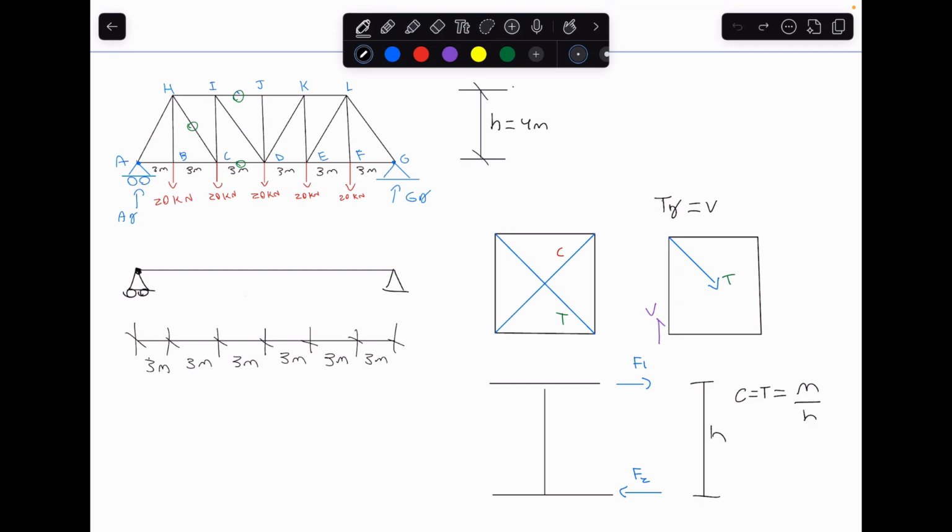Next, we're going to use the shear force diagram to get the diagonal forces using the single diagonal assumption. Basically, the assumption is that we used to have something that looked like this in the panels, one brace in compression and one brace in tension, but all of the compression braces have buckled. Therefore, we're left with a bunch of single diagonals. Also, I should note that we're really only concerned with the y component in these diagonals, and we're going to use the shear force diagram to determine the magnitude of that y component.